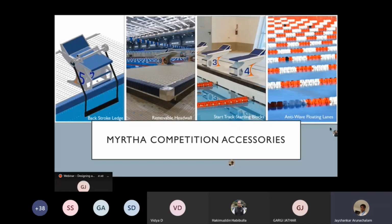So that's the backstroke ledge. The next one is the head wall, which gives the flexibility of creating a platform around the swimming pool on the shorter ends, and most of the time also allows four-way water circulation. The third one is the starting block. You can see the complete detailing, including the fin behind, the slope, and the kind of material. There is a provision for a kickstart system, which all gets assembled into the starting block. Then these are the anti-waving links on the rightmost end.